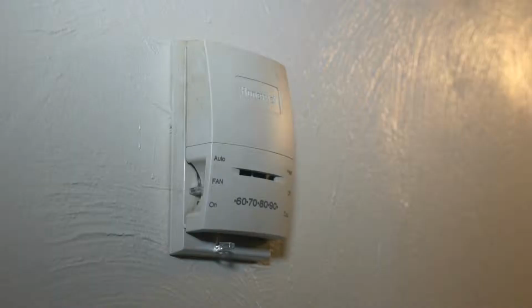After we make sure that our combustion appliances are off, we'll go ahead and turn on our furnace air handler. Now remember, we're not turning on the heat mode and we're not firing our furnace. We're simply turning on the circulating fan in our air handler so that the supplies and returns can go ahead and start to move air and show us any pressure differences that are being created by this.